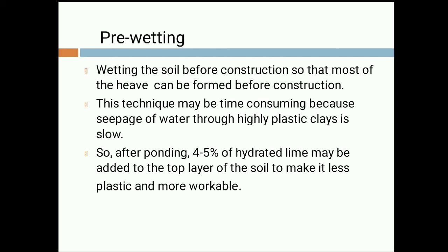This technique may be time consuming because seepage of water through highly plastic clay is slow. As we have discussed in the last lecture, the plasticity index of the soil is very high, and the water will go deep inside very slowly, and the swelling of the soil will not happen in 1 or 2 days. It needs 15 to 20 days, and because of that there can be delay in the construction of the project. So after ponding, 4 to 5% of hydrated lime may be added to the top layer of the soil to make it less plastic and more workable. So basically 4 to 5% of hydrated lime is added to change the property of the soil.